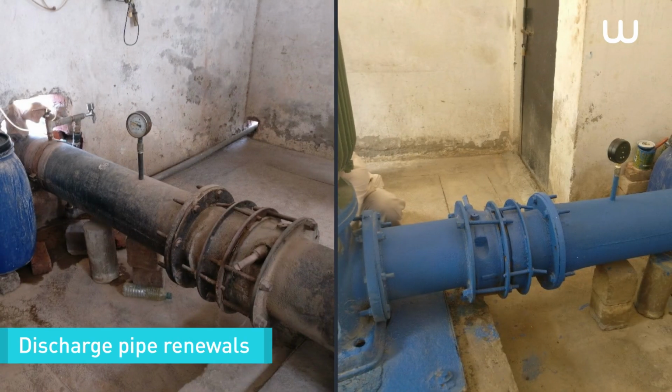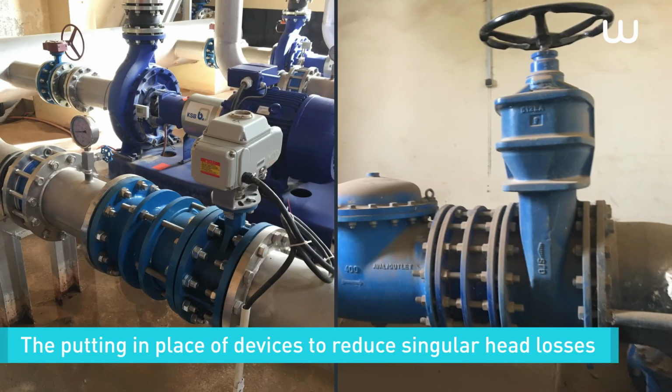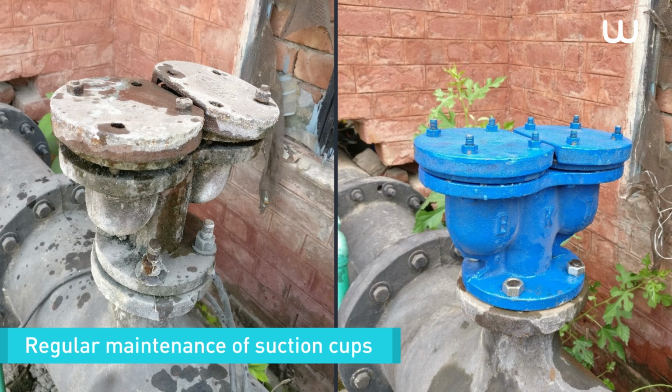Secondly, various actions can be carried out at the level of networks and pumping sites' operating modes. A linear and singular head loss optimization and reduction program on networks can permit pumping energy consumption to be reduced, namely thanks to discharge pipe renewals if they're undersized or if pipe walls are extremely rough, or if the pipe section is reduced owing to clogging or corrosion. The putting in place of devices to reduce singular head losses on the network, such as valves, filters, production meters, and block valves. A regular maintenance of suction cups, which ensures discharge pipe pressurization without air pockets generating singular head losses along the pipeline.